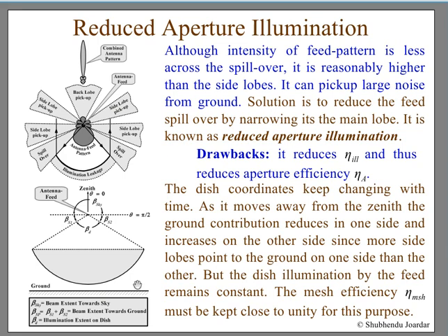Apart from any source, if there is no source and the sky is cold sky, but the position of the antenna changes, you will see the temperature of the system also change. That is because of all of these effects, because these angles will be looking into different places, and also this leakage contribution will play a big role in that.